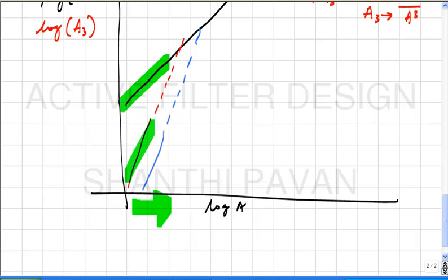Okay. So if you had one filter like this, and another one, when I did the intermodulation, gave me a plot like this, which do you think is more linear? The blue one is more linear, right? And this hypothetical point where the two lines intersect, the line of slope 3 and the line of slope 1, will eventually intersect. Mathematically, if I just extend those lines, they will intersect at some point. Please note that it's a fictitious point because in practice you will never get a third harmonic of the same strength as the fundamental. But the farther that point is along the x axis, the more linear the filter is.